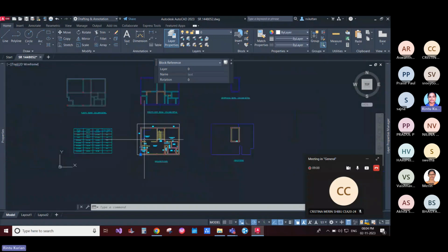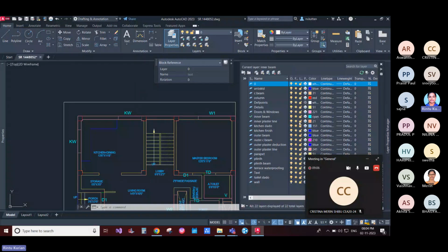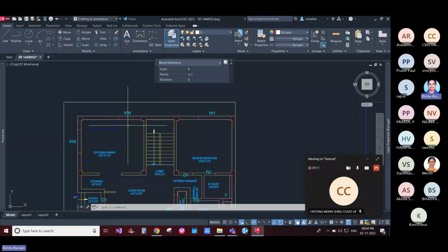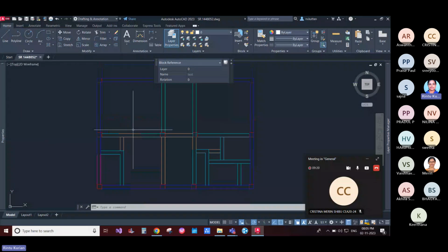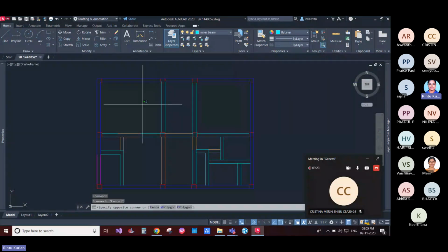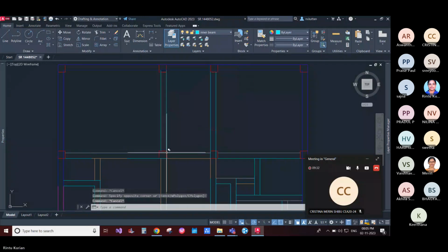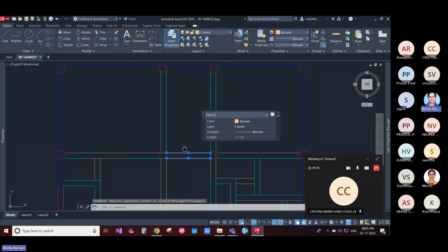Okay, now a set of CAD utilities have been drafted. The explanation for the same has been given in a previous session, and I'll give a document stating each CAD utility, its name, and the purpose of each CAD utility. Now, coming to the structure drawing part, there are 4 different types of beams used over here. Outside beam or outer beam, inner beam, which is coming within the building, and below this portion there is a wall. If there is no wall supporting the slab, where there is no wall beneath the beam, it is called a ceiling beam and it's denoted separately.